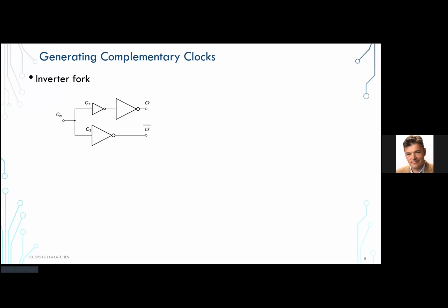Yeah, exactly. So I have some intrinsic delay and some fan-out induced delay. So first, to size this optimally, what should be the capacitance here? Or how should this guy be sized?